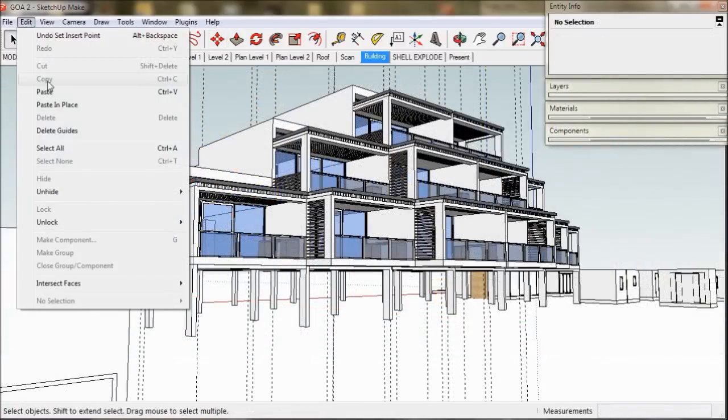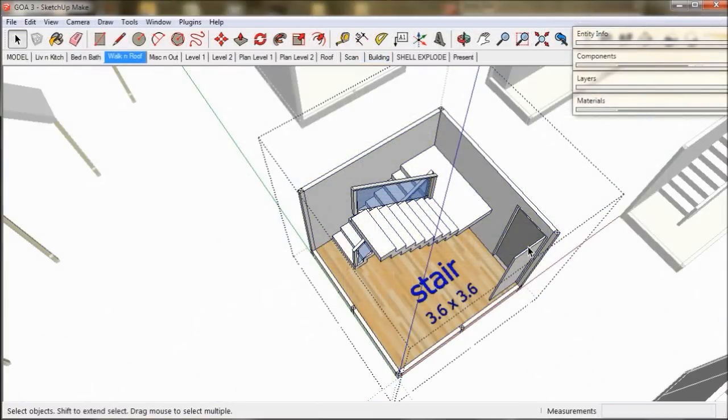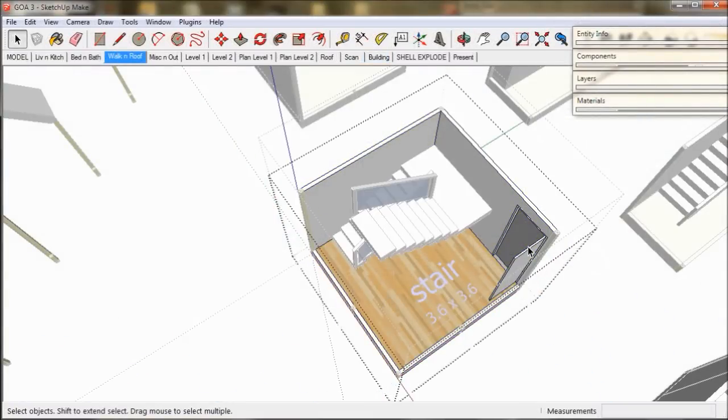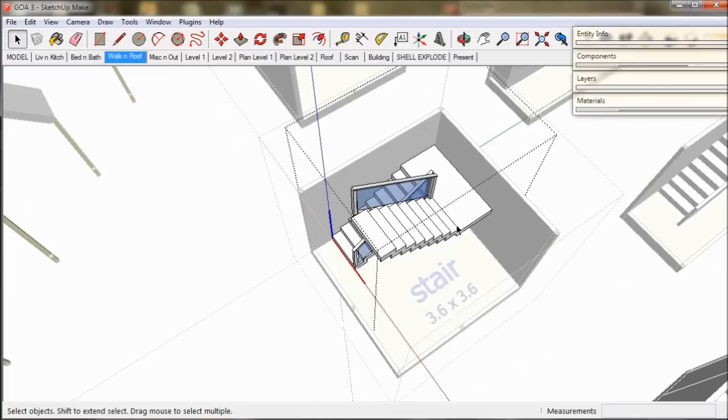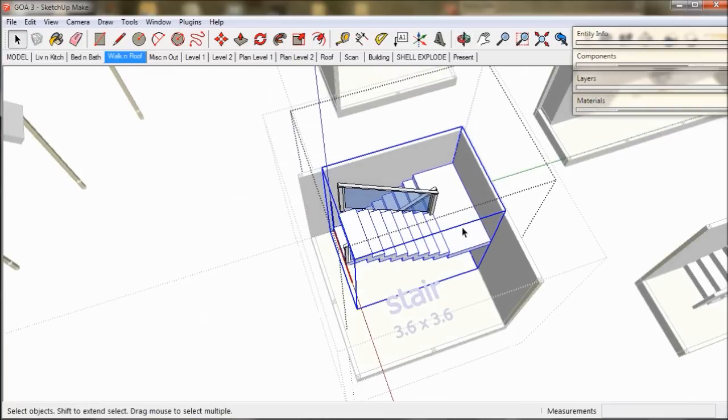Now we'll move on to the stairwell. We use this standard 2-flight module and alter it to suit. Get rid of the doors first and adjust the mid-landing and stairs so we can get an elevator shaft into the centre of the stairwell.